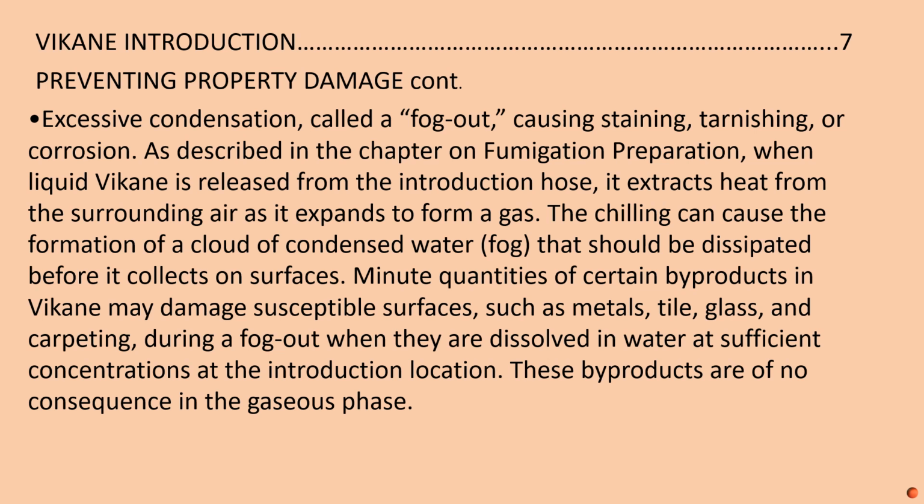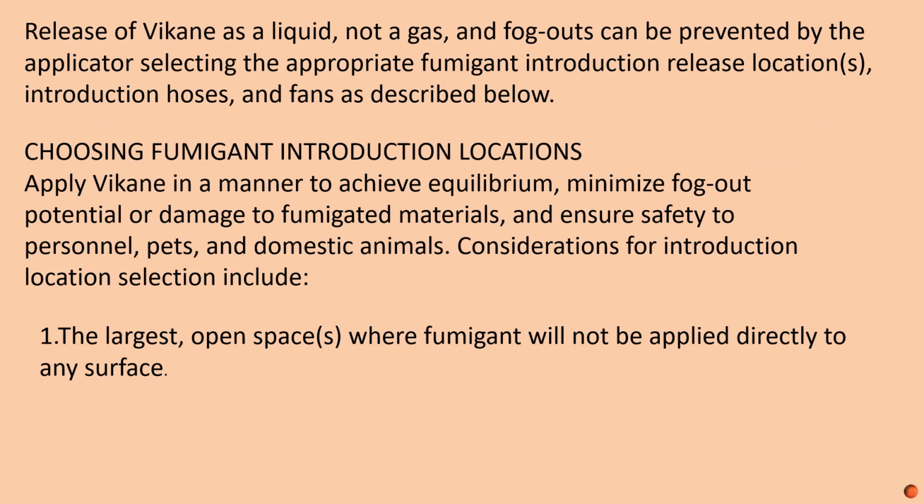Minute quantities of certain byproducts in Vikane may cause damage to susceptible surfaces such as metals, tile, glass, and carpeting during a fog-out when they are dissolved in water at sufficient concentrations at the introduction location. These byproducts are of no consequence in the gaseous phase. Release of Vikane as a liquid, not a gas, and fog-outs can be prevented by the applicator selecting the appropriate fumigant introduction release locations, introduction hoses, and fans as described below.